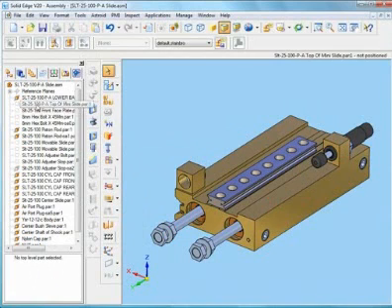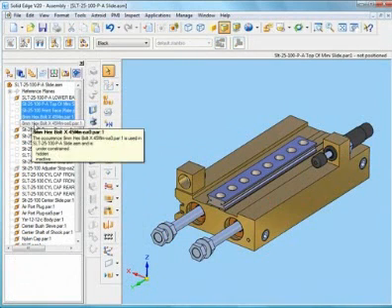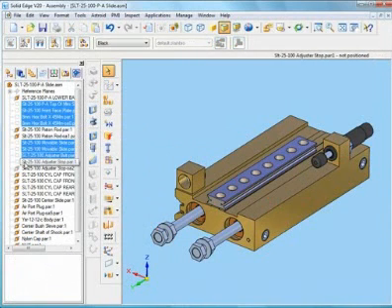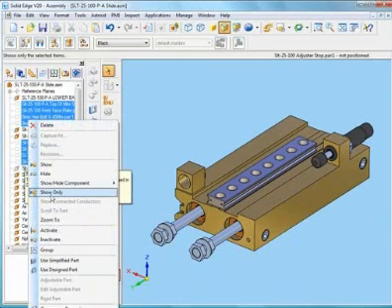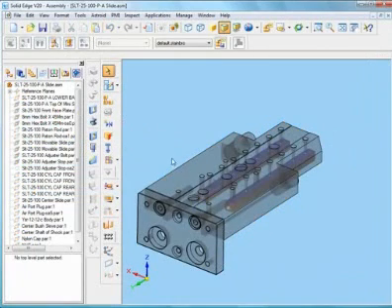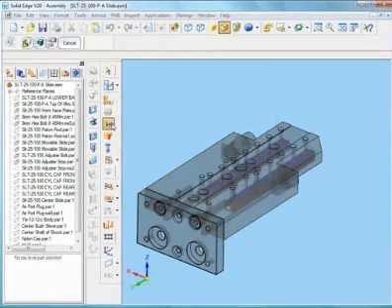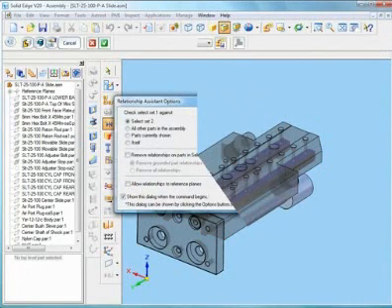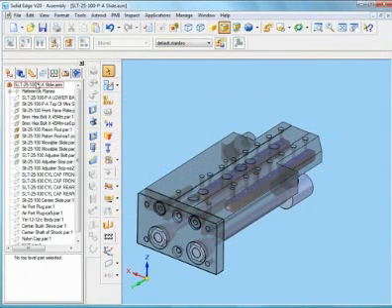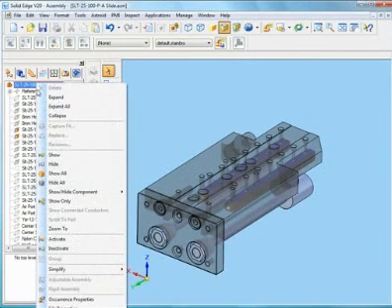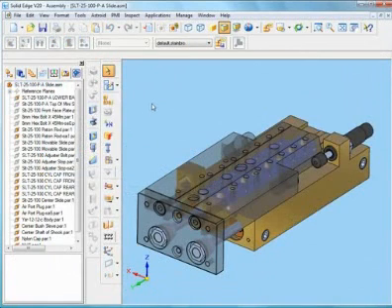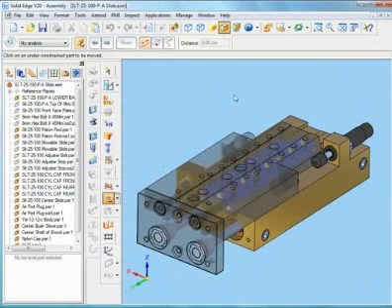To allow movement in the assembly, we deselect the piston rods, freeing them to move in and out of the slide body. The base is now constrained, so we turn our attention to the slider. With the slider displayed, Solid Edge Auto-Constrain is used to add relationships in exactly the same way as for the base. With both the slider and base now constrained, all the parts in the pneumatic slider assembly are displayed.